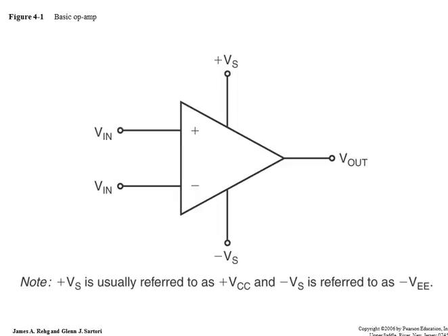Okay, now what happens is that the operational amplifier is going to have an infinite impedance on the input. So an ideal guy, infinite impedance, I'm not going to use any signal that I'm getting. I'm not going to degrade the signal any, I'm going to just use it. It's going to have an infinite amount of gain for the output, and the output impedance is going to be 0.